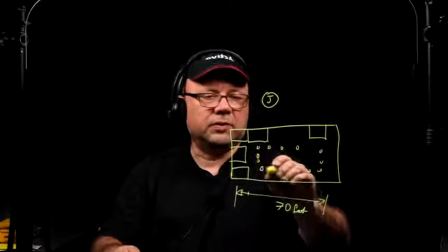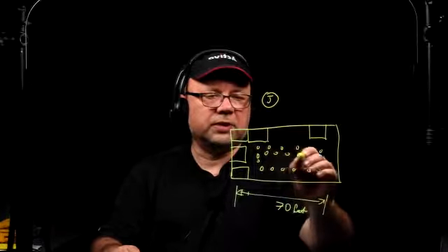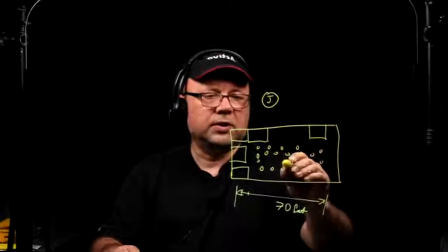Based on that, you can scale it to this drawing here, and you're going to be able to tell what is 4 feet. So the J hooks should be 4 feet apart. My suggestion is just to place a bunch of them around the perimeter here of the inner hull, 4 feet apart. There's going to be one set of the J hooks, and there's going to be another set of J hooks.